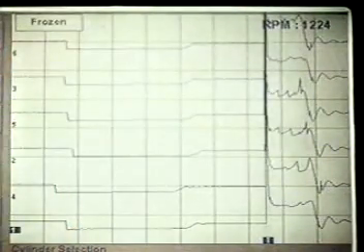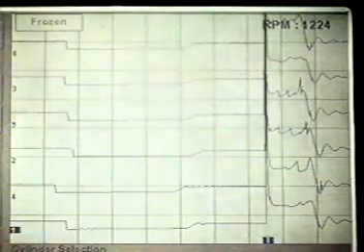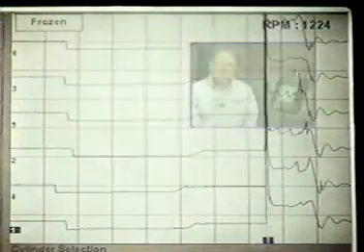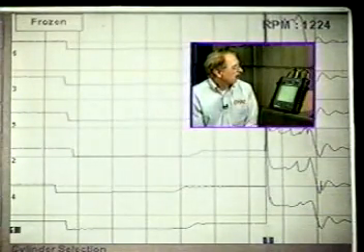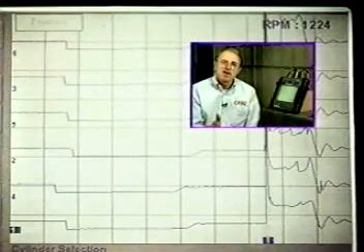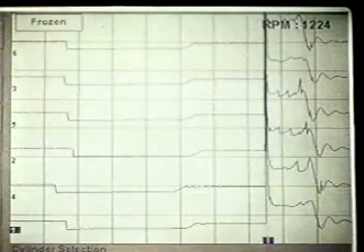As you can see, I've frozen the pattern. And again, the scope is on a 1 millisecond time base. You will see slight variation because as the RPM increases, we will turn on primary sooner to ensure that the coil gets sufficient charge time. As you can see, we still have a little bit of misalignment here. This is not a problem. At 1 millisecond per division, you can see that we are still within no more than 500 microseconds variation between the points of primary turn on.